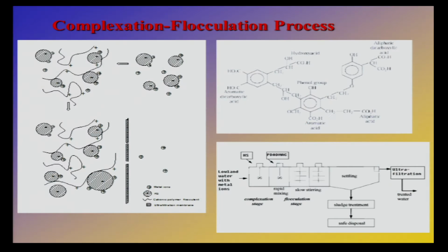And then, of course, after we've done the mixing, we need a settling tank. So the solids are going to settle out of the fluid, and the waste solids or the other solids will form a sludge. And then the liquid, which is coming off, is going to be ultrafiltered to give you the treated water. Now, in our case, the thing that we're interested in is actually the sludge, because that will contain heavy metal ions.